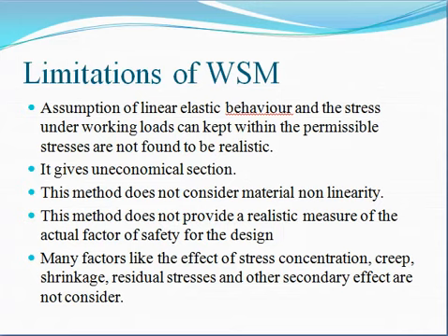But in actual practice, the stresses may exceed their permissible limit in some cases. In case of accidents, in case of some unfavorable condition, these stresses may exceed their permissible stress limits. That's why this is not practically possible. So this is the limitation of the working stress method.